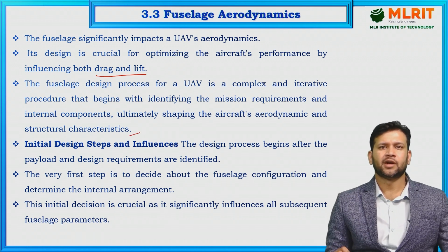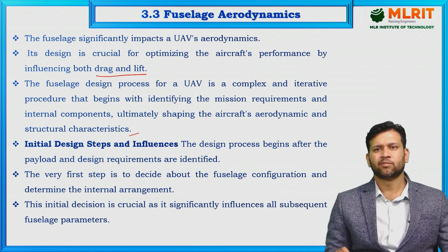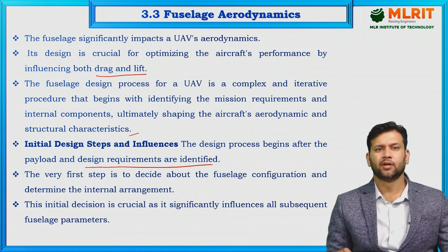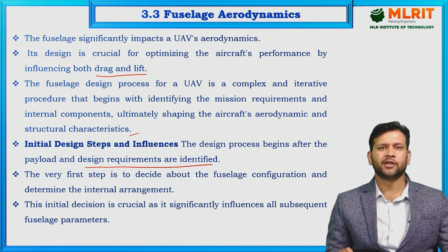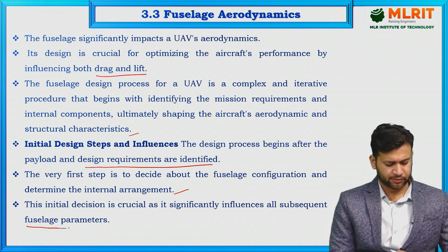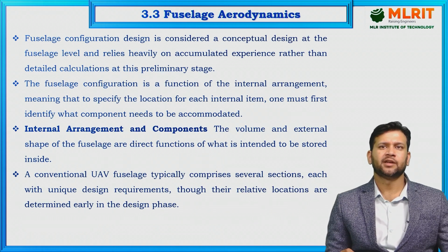Initial design steps and influences. The design process begins after the payload and design requirements are identified. The very first step is to decide about the fuselage configuration and determine the internal arrangement. This initial decision is crucial as it significantly influences all subsequent fuselage parameters. Fuselage configuration design is considered a conceptual design at the fuselage level and relies heavily on accumulated experience rather than detailed calculation at this preliminary stage.